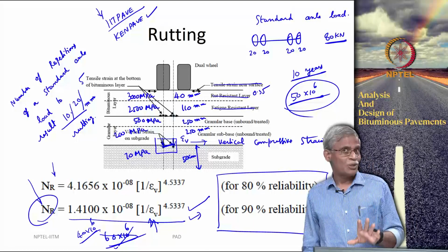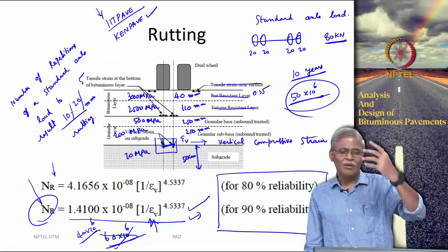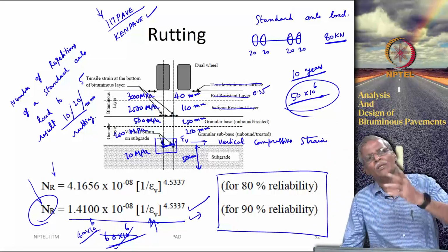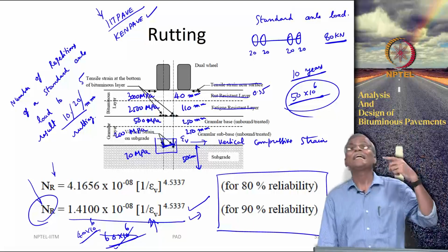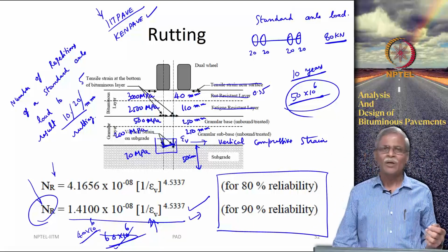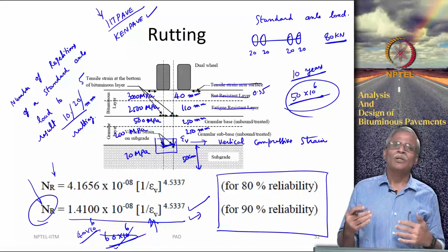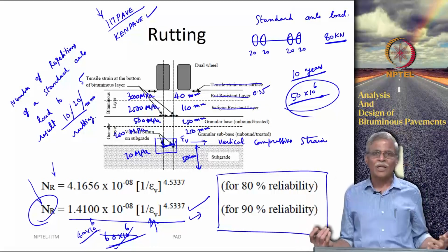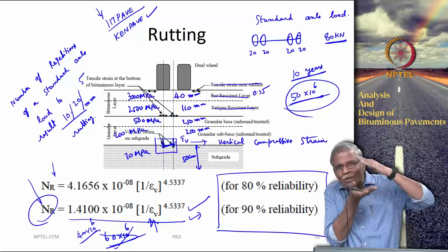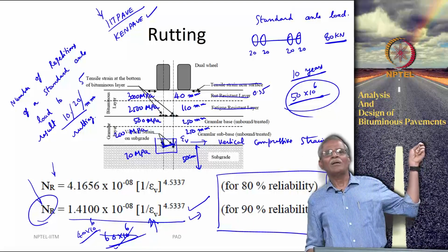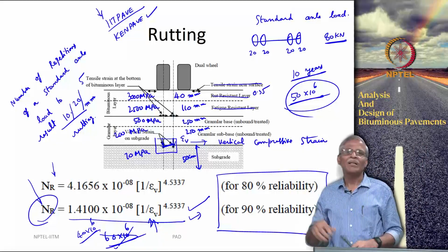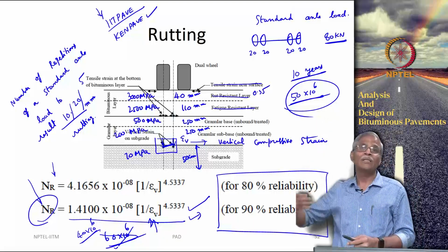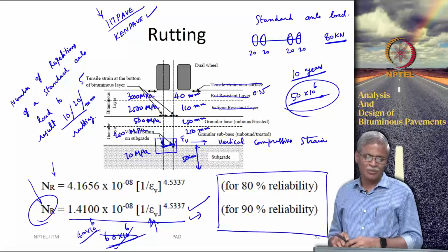And there are many interesting issues related to this, and this is why bituminous pavement engineering becomes very interesting. Now, you can increase the thickness, you can increase the modulus. So, now you need to do some kind of a sensitivity analysis to find out what kind of layer thickness combinations, modulus combinations will result in increased resistance to rutting, but at the same time try to reduce the cost. So, you remember the chart that we showed in the starting, wherein first you collect the input, then you do the analysis and then you pick the realistic section, that is where this comes in here.